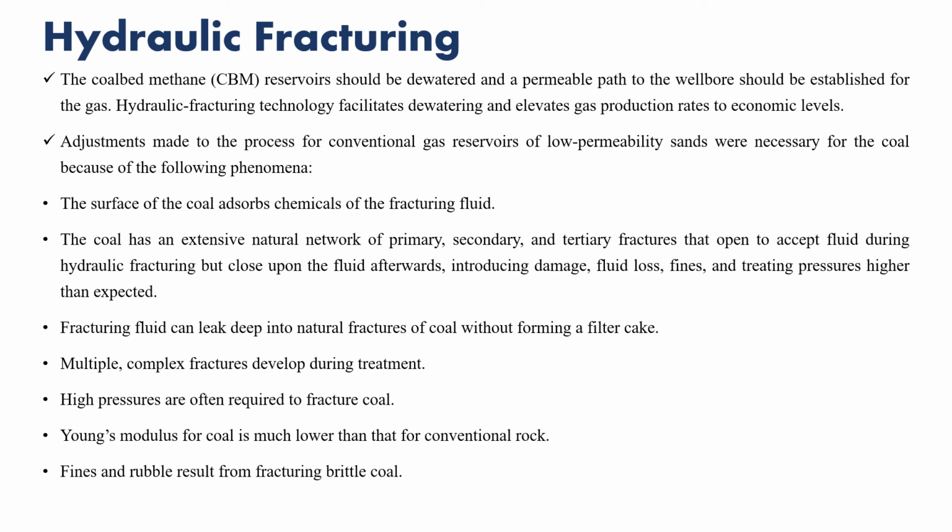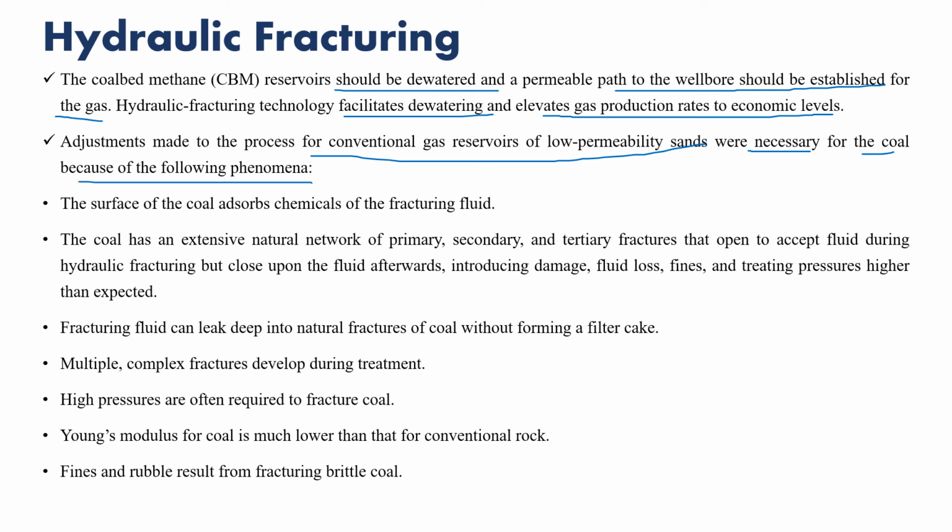Hydraulic fracturing. This is just an outline, it won't be used much. The coal bed methane reservoir should be dewatered and a permeable path to the wellbore should be established for the gas to produce. So hydraulic fracturing technology facilitates dewatering and elevates gas production rates to economic levels. That is right. Adjustments made to the process for conventional gas reservoirs of low permeability sands were necessary for coal because of the following phenomena. Because coal is a special reservoir, we should make some adjustments.